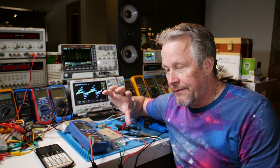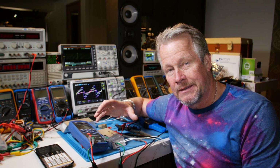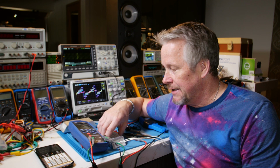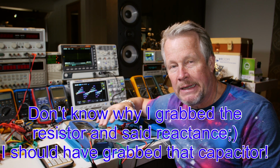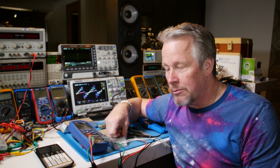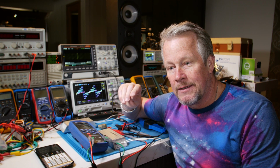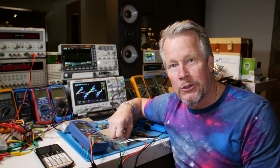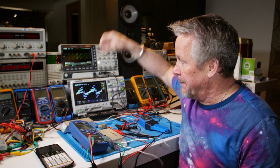If you have some inductance, capacitance, and resistance in your impedance measurement, that's why we call it impedance, because it's not just resistance or it's not just reactance. It's everything combined. It's impedance, and we call that Z. So Z equals so many ohms, and we can measure it here. So besides this ohms measurement, we'll also get a phase angle, okay? And that's what is really cool here. I'm going to show you how that's done, and in future videos we're going to do a speaker impedance.